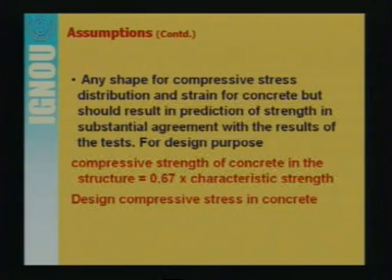Now the question is, to analyze the structures, we should know the shape of this stress strain diagram also. So, the code says that the stress strain diagram can be taken of any shape, provided that the area under the curve gives results which are in prediction of the strength in substantial agreement with the results of the test. Meaning you can assume any shape, but the result ultimately you are getting should coincide with the results that we get from the experiments. For design purposes, we take the compressive strength of the concrete in the structure as